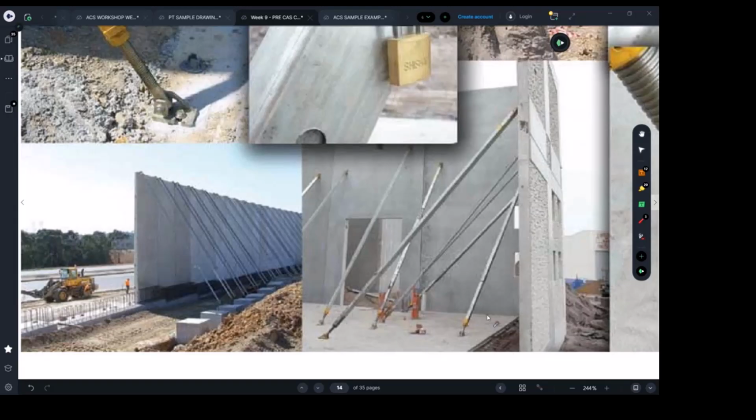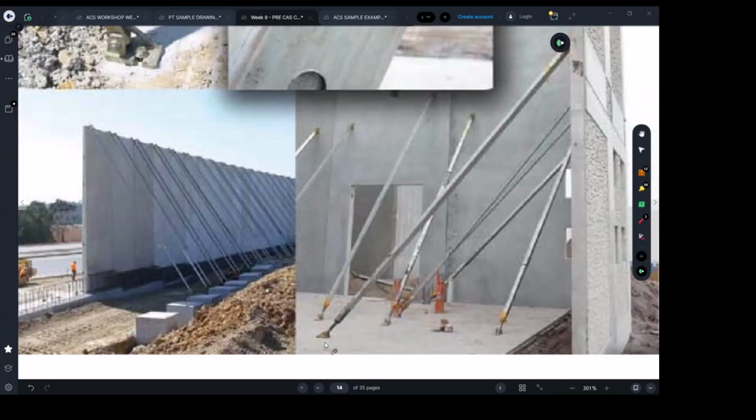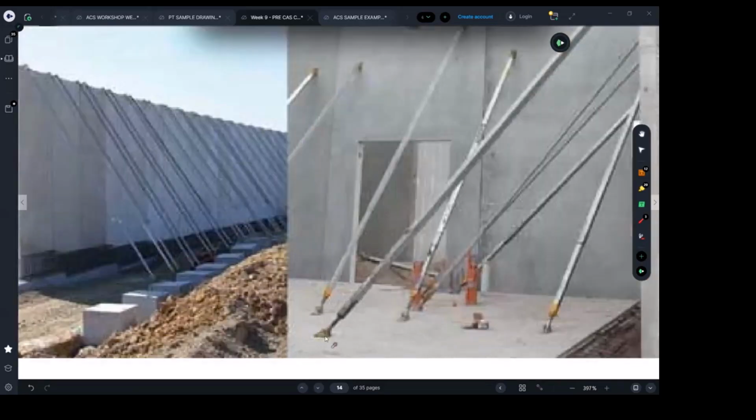If you had a better planning where you will be pouring your final slab, then you can prop it from the slab. But you have to make sure architecturally this won't be compromised, because maybe those temporary holes may not work well for the architect.